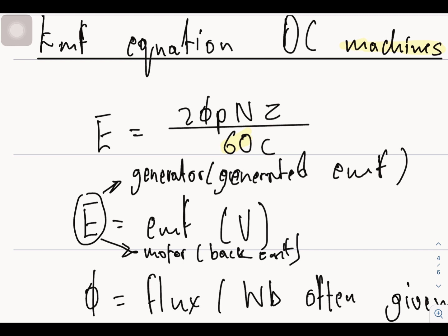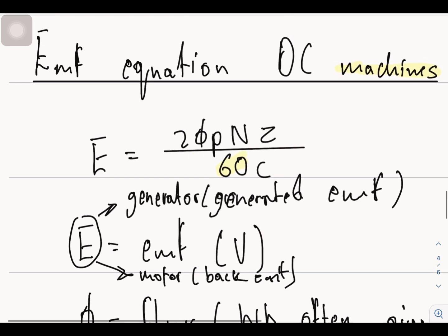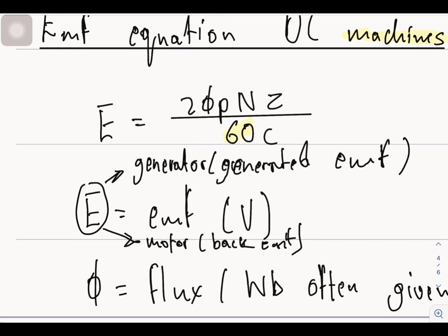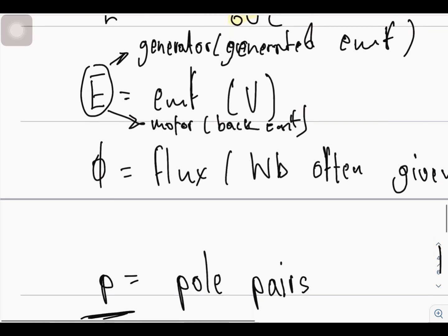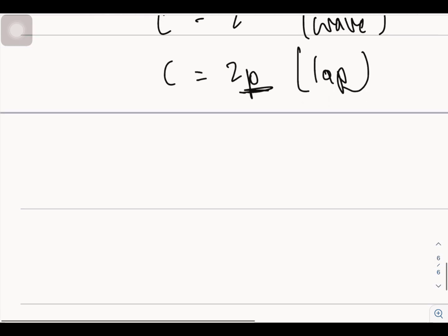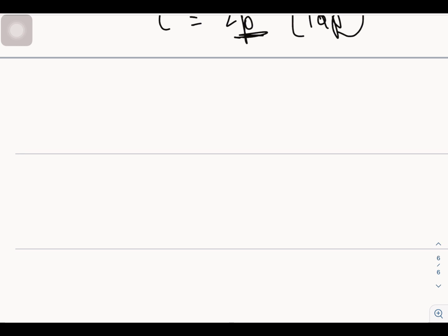It enables the motor to regulate or control the current, so it is not too much. A motor needs a starter because when the armature is standing still, the back EMF is 0. And the back EMF is what controls the current. We have to use a starter and get the motor to a running speed so that the back EMF starts regulating the current. I'll make another session for that.